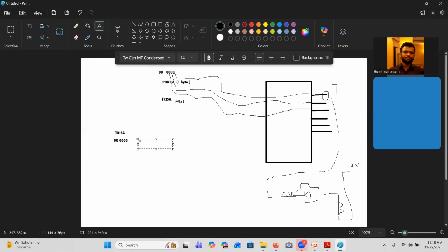After that, I will set the value of port A; I have to make that bit 0. Only then will it become low. As it becomes 0, automatically the LED will try to glow. So what I have to do, I can write a C program here: PORTA equals PORTA AND with 0xFE. Can I do it like that? So all bits are made 1 except the least significant bit.